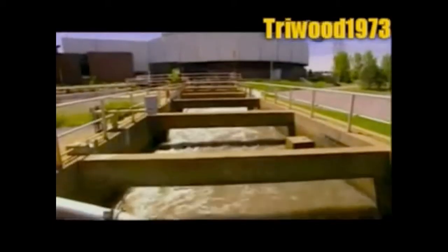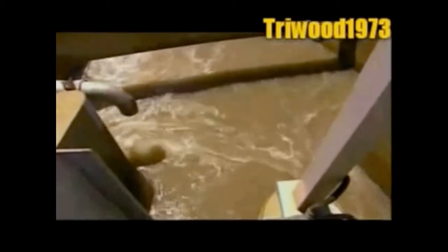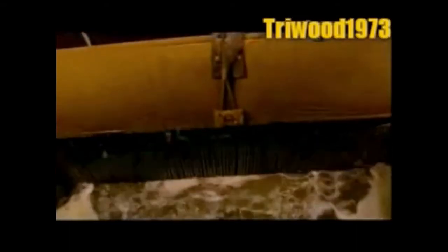Along the way, it's sprayed with either aluminium sulfate or ferric chloride, two chemical coagulants. They gradually transform phosphorus in the water from liquid to solid, so it can be removed later on. Once the water reaches the treatment building, it flows through screens. This preliminary filtration removes any solids larger than 2.5 centimeters in diameter, such things as stones, paper, and plastic.